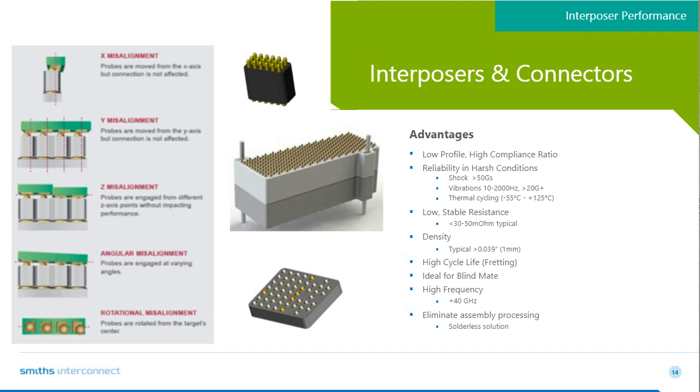Lastly, the added benefits of an interposer solution is the tolerance stack-up absorption that they can provide over other interconnect options. As you'll see here on the left, we're illustrating the different degrees of freedom that are allowable. X and Y will change based on the chosen pitch versus the pad size being used in the design. Z is determined by the amount of travel a particular solution may be designed to have. And then you also have the added angular and rotational misalignment capabilities an interposer can provide. Again, as to how much will vary greatly by design.